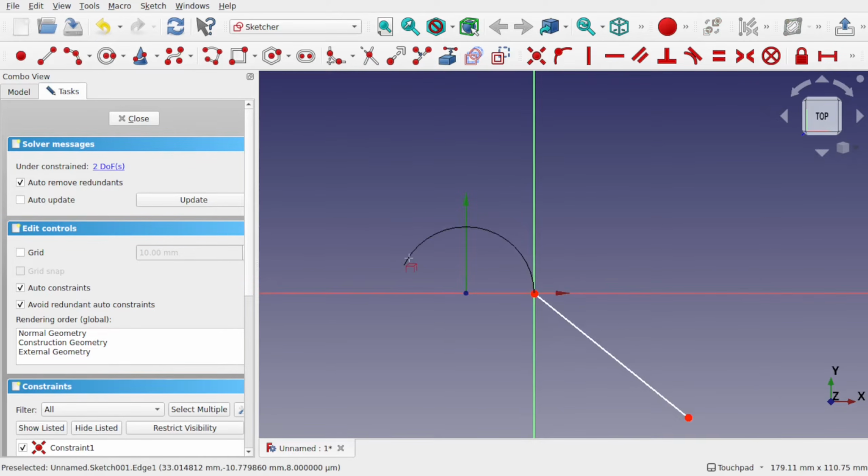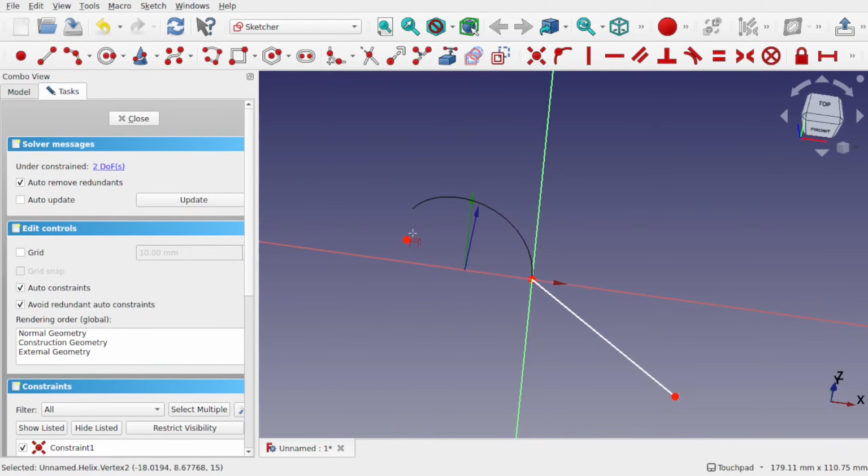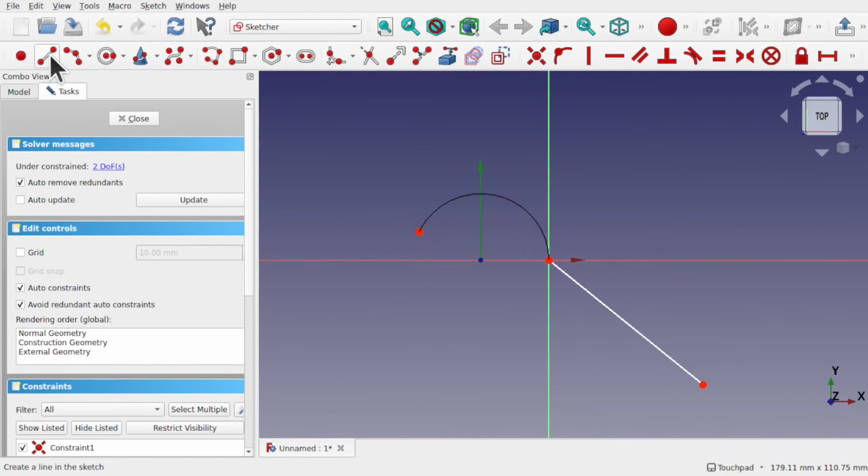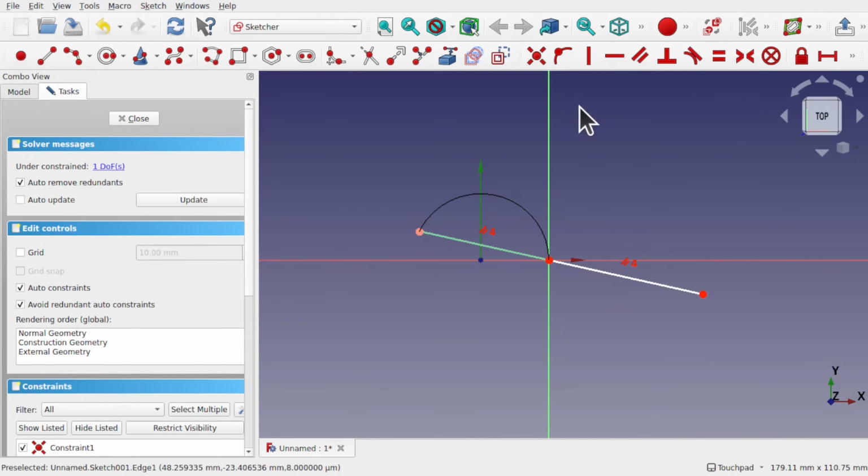So let's import this point. What's happened is the point is being projected down on the planar surface, so along the same plane. Click top and come over to the line. Use a line, constrain to this point, and constrain to this one. So we've spanned those 2 points. Now I'm going to take this line and this line and make a parallel constraint to keep those in line. Next, let's select the line that connects these 2 points and make that construction geometry.